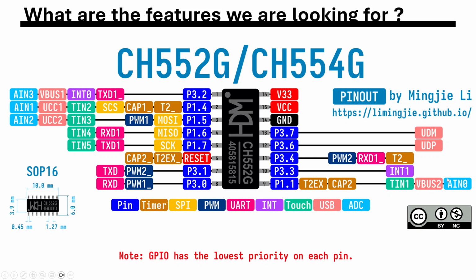USB 1, USB 2, which are used if we are mapping on USB-C. Then if you want specific power considerations to be taken into account, then VBus 1 and VBus 2 work, and CC1 and CC2 work as negotiations, right?